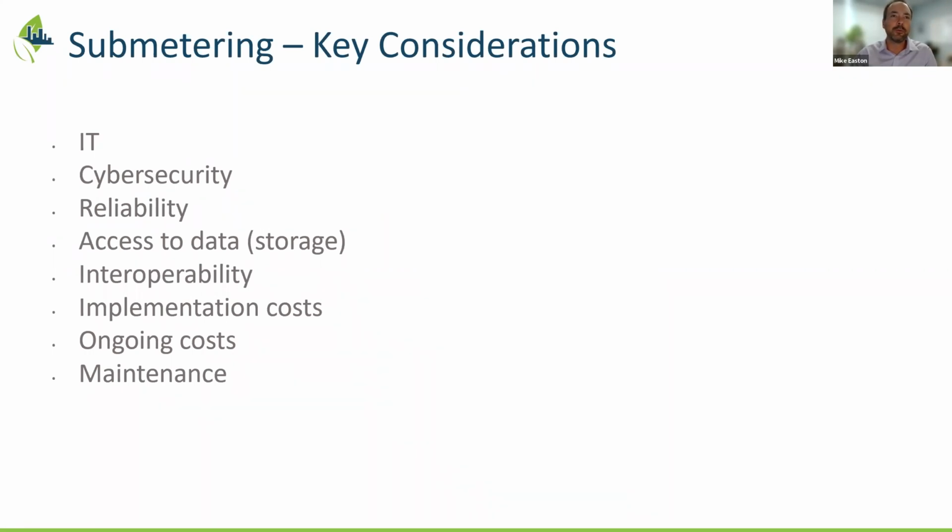One of the things that more advanced energy management systems do is keep continuous track of these meters and automate a response to somebody at the property or a vendor to let them know that there is down communication, so they can take proactive steps to improve or fix it, instead of when you go to look at the data 3 months later and you have zeros or just blanks. That's too late. One of the better technologies is this instantaneous feedback from the systems to let you know if a meter's down.